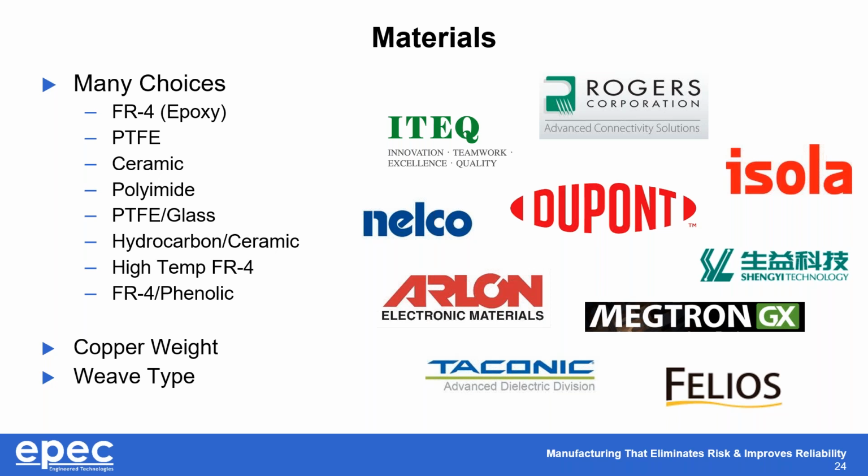The other thing that we see is copper weight. We happen to be very prevalent in heavy copper printed circuit boards, because we have a huge supply chain. We negotiate with the manufacturers both here and in Asia every year for 4-ounce interlayer copper cores, because we know that our 8 biggest customers are going to use so much of it, and because we know that a lot of these manufacturers don't like making the heavy copper cores.